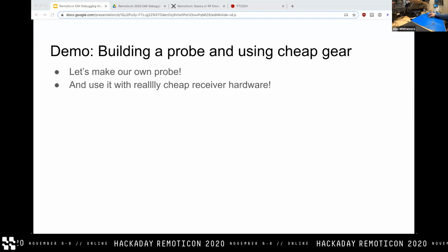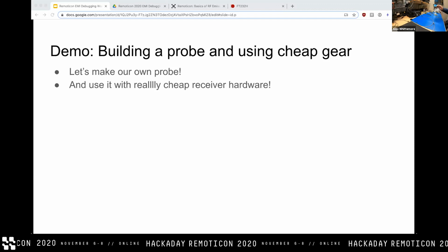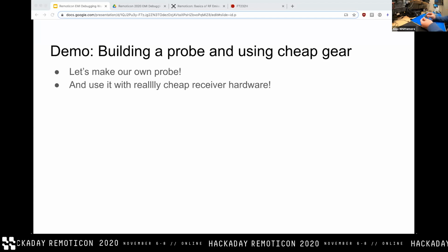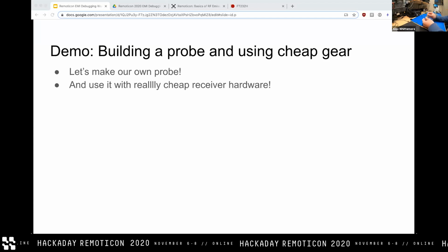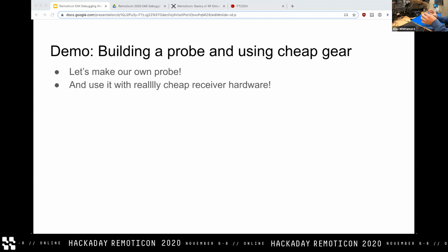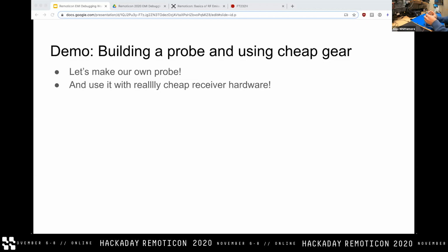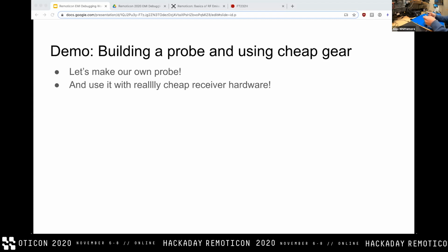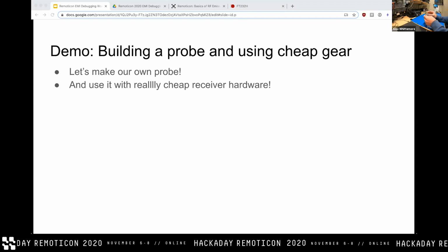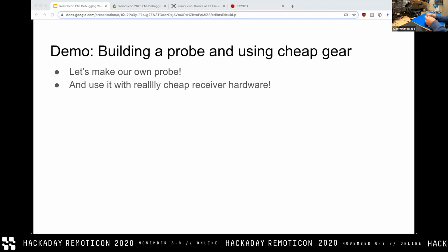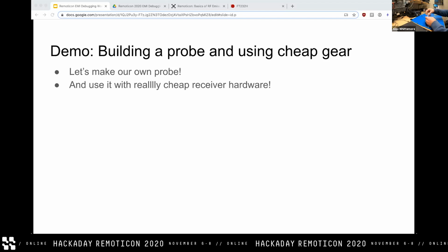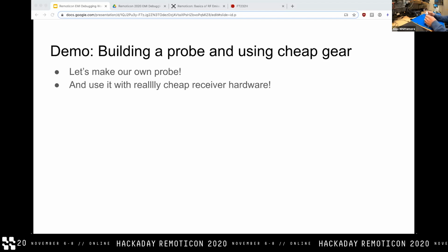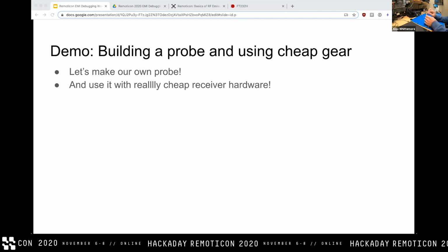I didn't want to offer a shopping list with a bunch of USB power supplies, even though I'm sure everyone already has one anyway. I wanted something that was easy. Basically, a bias T works by setting a DC voltage on the input to the SDR, and then this device is powered by that offset voltage on its output side. So if we plug this guy in, output to the SDR, it will light up with power because the bias T inside the SDR is powering it.